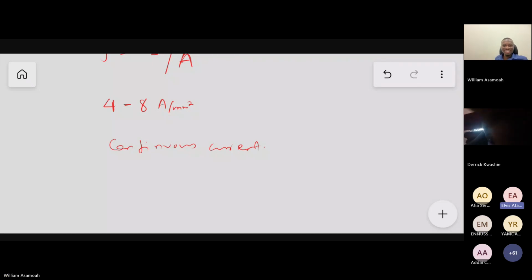So I think that the reason why we are using the continuous current is because during the warm-up process, that is the one that is being used. The inrush current was what was generated, what came into the system at first, but that's not what is moving through. Exactly. That's very brilliant. I like that. The reason why we don't use inrush is that inrush lasts only briefly.